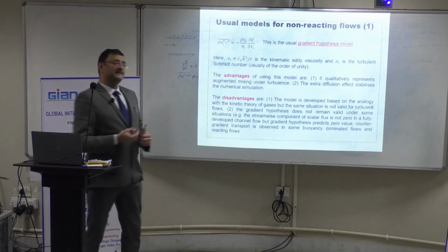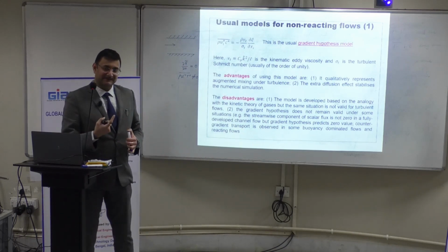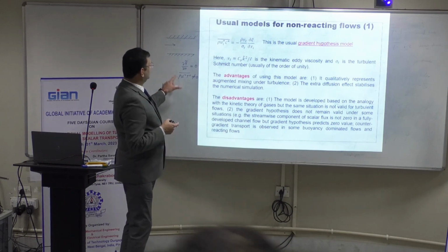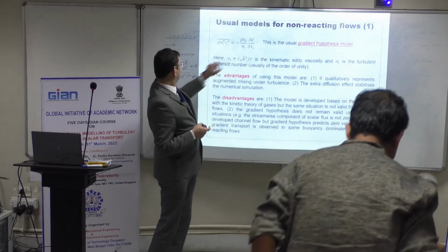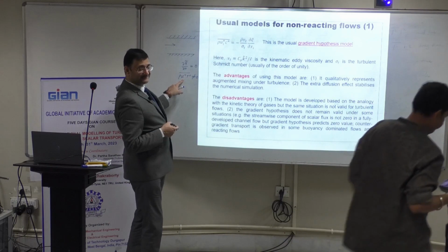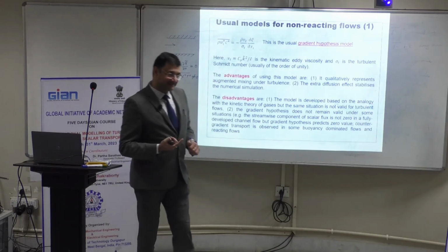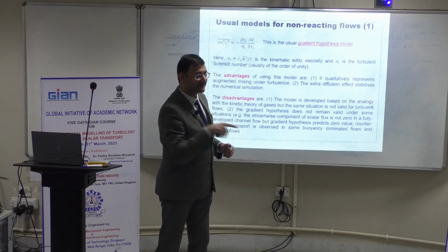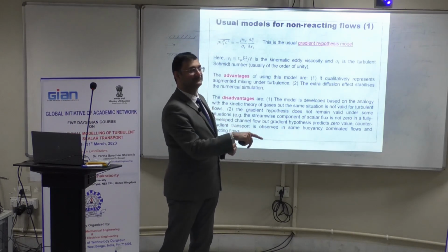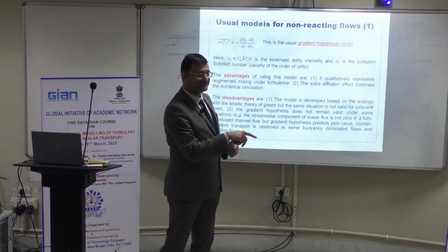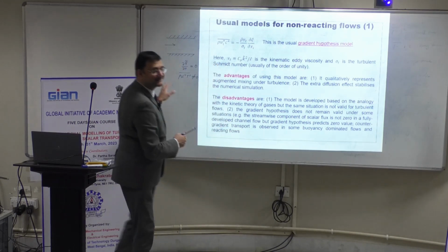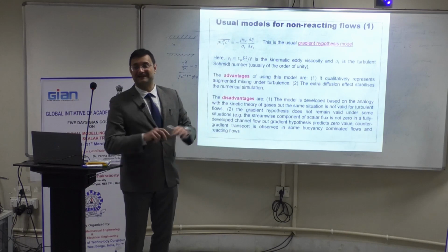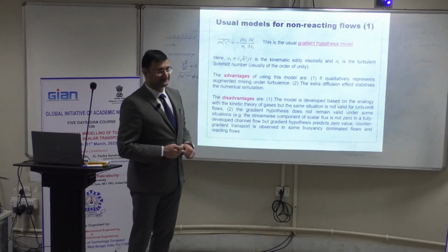Because think about the boundary layer theory. Essentially, for this quantity, the second derivative in the wall normal direction is much, much greater in comparison to the second derivative in the streamwise direction. So even if you incur some error in evaluating this, it doesn't make any huge difference.